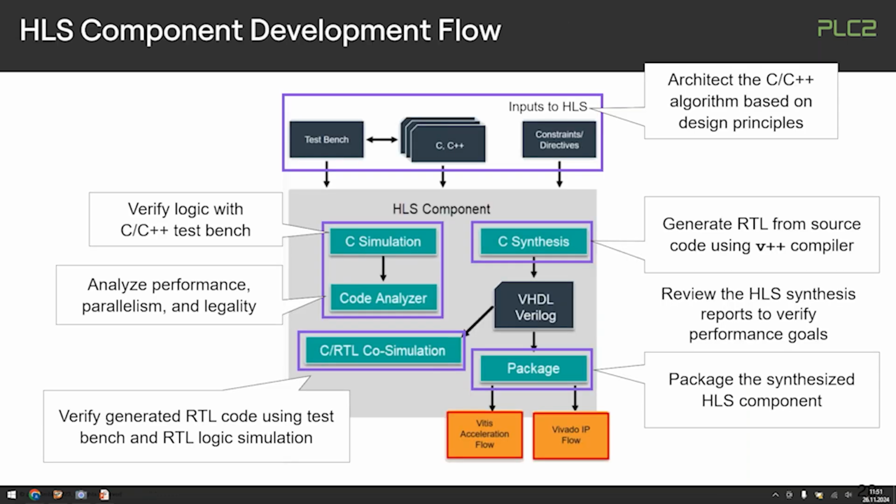When you look into HLS, just to get it mentioned in here, it's really all about keeping your effort of function closure on the C level. So you have test benches for your C code, and you basically try to get the most out of it. And then you will translate it into some suitable HDL code through the process of the compiler.